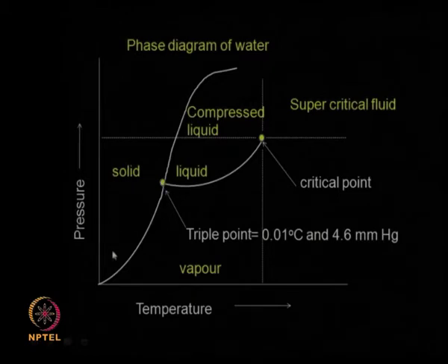So if you are operating in this region, if you are doing a lyophilization, all you need to do is reduce the temperature so that the ice is formed, and then you play around with temperature and pressure so that the ice directly goes into vapor. So by doing this alternatively, we can slowly remove whatever water is present to a vapor form.